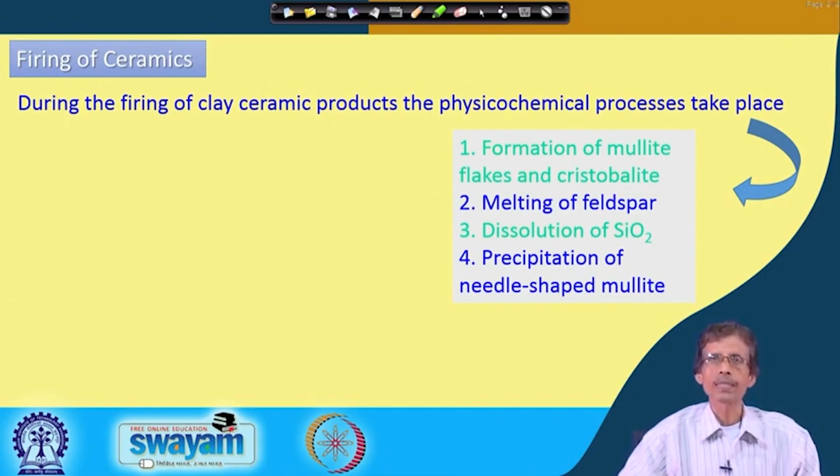So these crystals, basically the mineralization forms, are what we get during the firing process, because evaporation is taking place, then the high heat treatment changes the material from one form to the other. And the two typical mineral varieties, we know, are the mullite variety of flakes and the cristobalite. So these two varieties can form while changing the typical character of that material, or its physiochemical behavior or property.